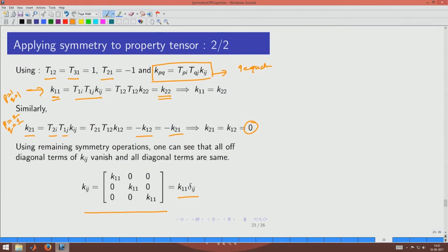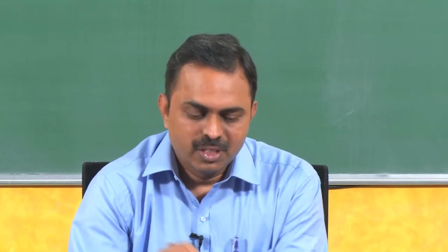So, the 4-fold symmetry is as good as infinite symmetry. But that is only because it is for a second order tensor. For a higher order tensor, it is not guaranteed. So, this is how the symmetry principle is coming of use. Neumann principle is helping us know that a second order tensor of symmetric nature can be reduced to just an isotropic tensor. Now, why isotropic is useful? Because later on we will have less numbers to handle.